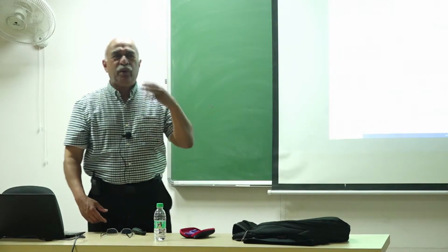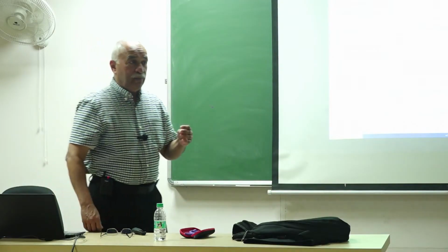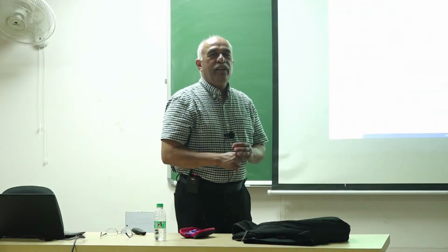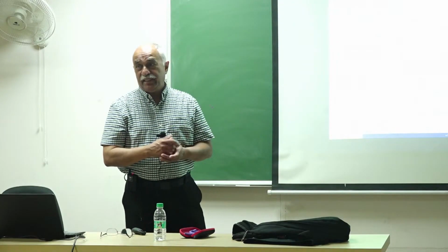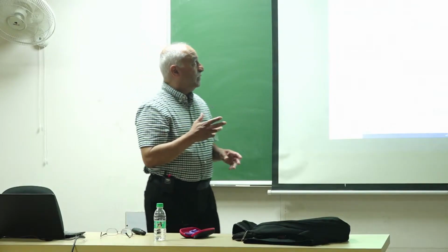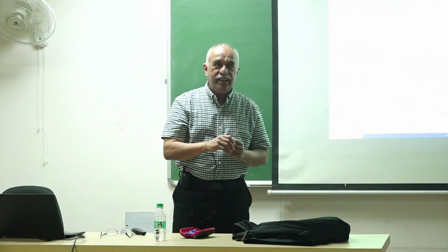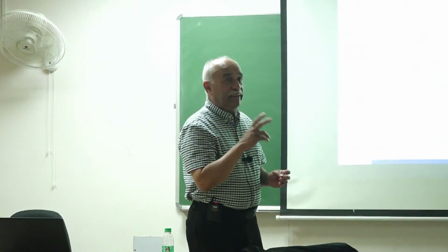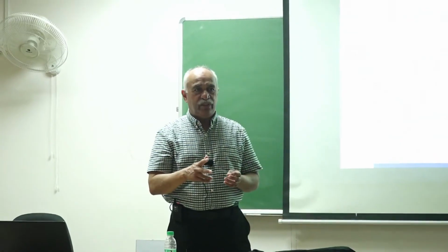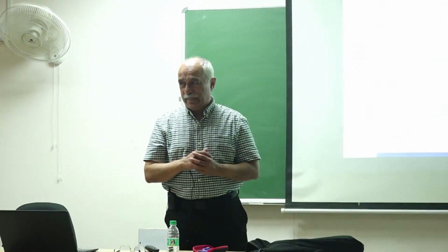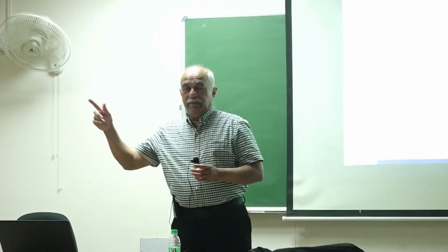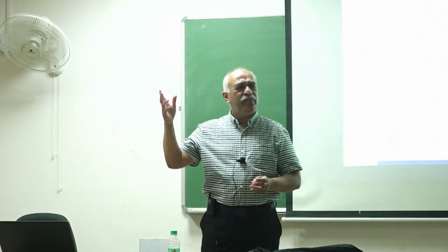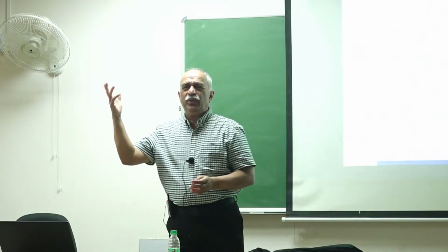We saw the Fourier transform, the DFT and everything. Fourier series you would have seen in your first year calculus or wherever. So you know very well that if you have a periodic signal, you can represent that signal using the Fourier series, which are complex exponential functions or sines and cosine functions at integral multiples of the fundamental frequency, or harmonics of the fundamental frequency. But then you go to infinity. You have a large number of those coefficients. Many of the high order coefficients may be very small, so you stop at some point.